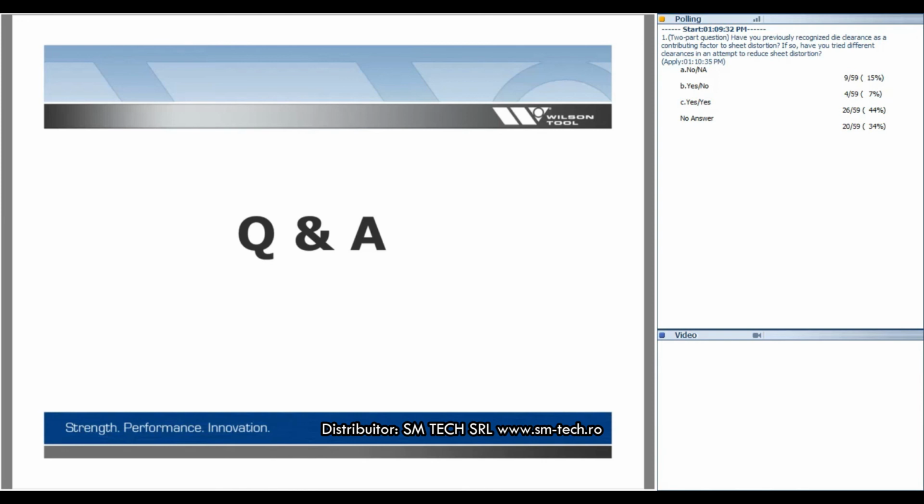What I can tell you is a lot of the forms that we use the sidewall pinch, they're often an offset, a foot, or often a stiffening feature. And what I can tell you, stiffening features, people tend to do an offset in the material 4 times material thickness just because that's what they've always done. We've proven a number of times, and this proof is you, the customer, have taken a traditional form, maybe a rib, 4 times offset,